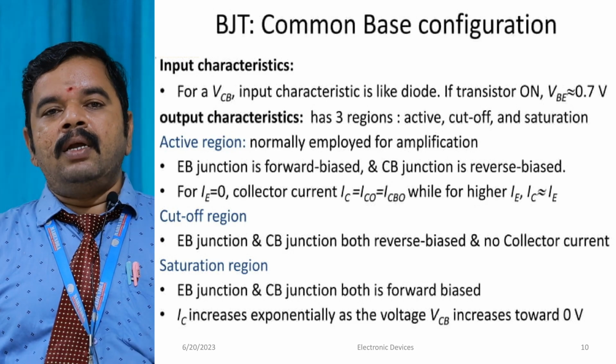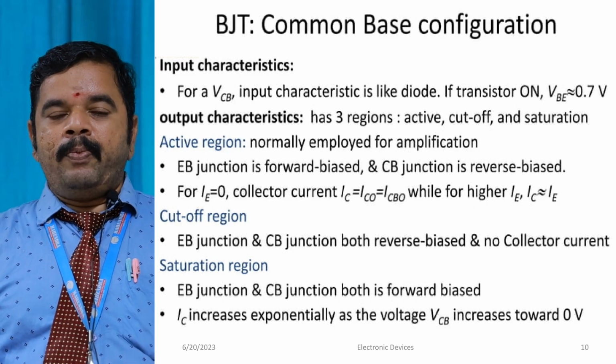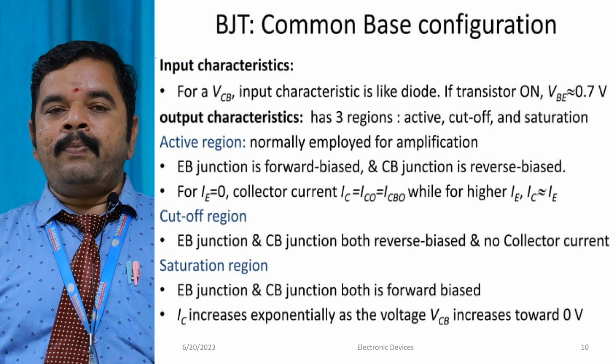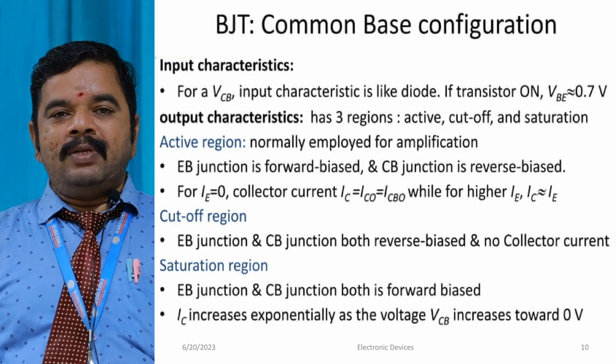We have to draw the curve between the input voltage and the input current for that constant output voltage. That is what we call the input characteristics.